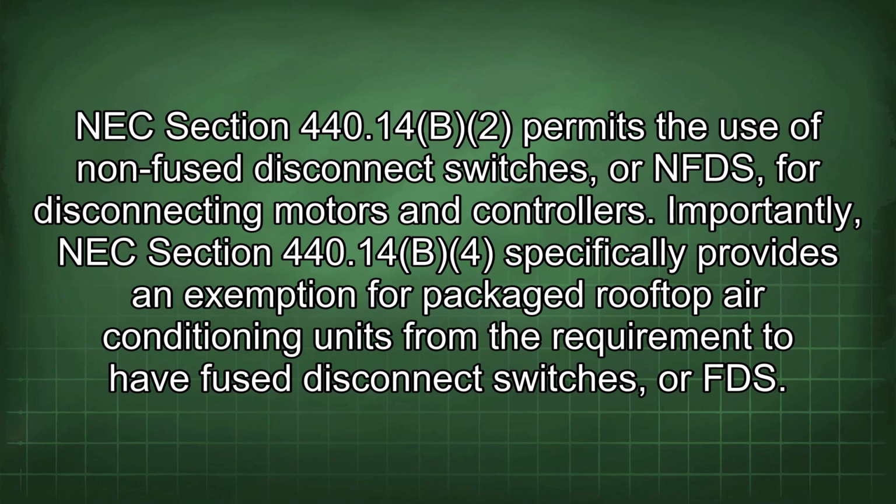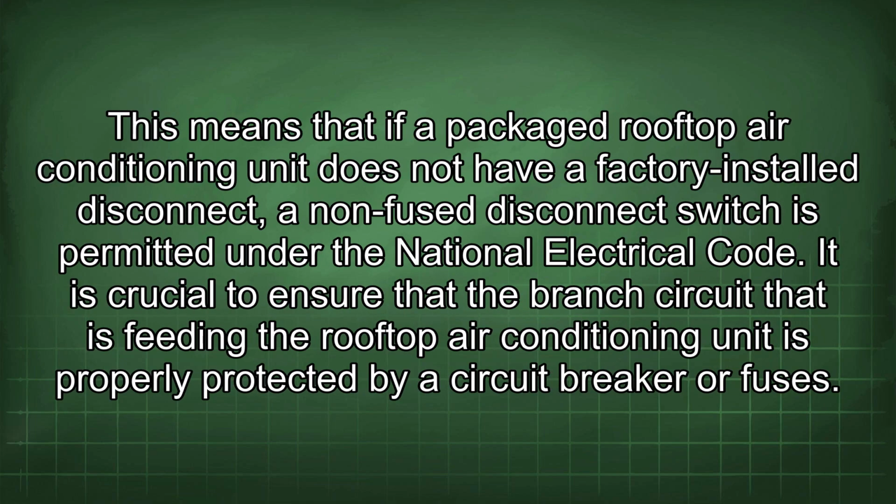NEC Section 440.14(b)(2) permits the use of non-fused disconnect switches, or NFDS, for disconnecting motors and controllers. Importantly, NEC Section 440.14(b)(4) specifically provides an exemption for packaged rooftop air conditioning units from the requirement to have fused disconnect switches, or FDS. This means that if a packaged rooftop air conditioning unit does not have a factory-installed disconnect, a non-fused disconnect switch is permitted under the National Electrical Code.